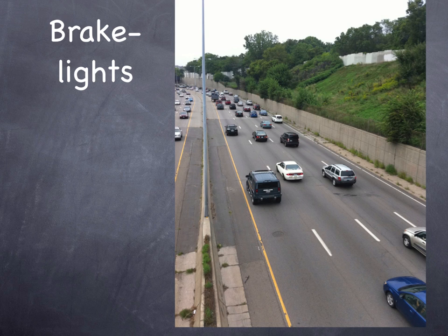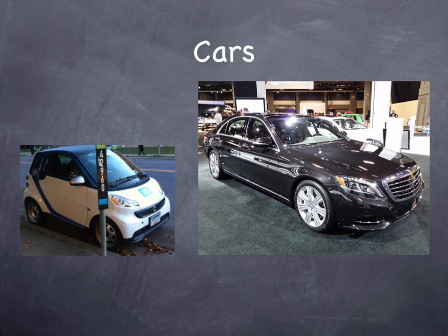If the car in front of you is very unpredictable, you're probably going to give them more space than if they're very predictable. If you can see ahead of them, you might give them less space because you can anticipate what they might do. When you were in driver's ed, what were you taught about the car following the car in front of you? Maybe you were taught distance, for instance, 4 car lengths. But how long is 4 car lengths? Well, it depends on how long a car is. A Smart for 2 is 2,500 millimeters. A Mercedes S-Class is over 5,000 millimeters.